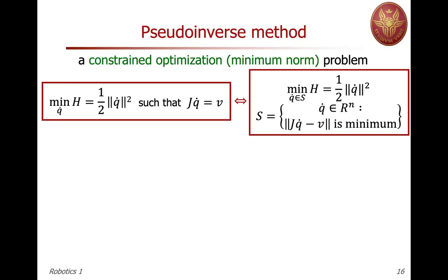So we're picking up a joint velocity from a special set, which is the set of n-dimensional velocities, because we have n joints, that minimize the norm of the velocity error. Indeed, we would like this norm to be 0. If possible, we will keep it 0, and then we will resume the previous formulation. But this formulation holds also if we are not able to satisfy the velocity V correctly. Why? Because V is not in the range of the Jacobian. This is our condition.